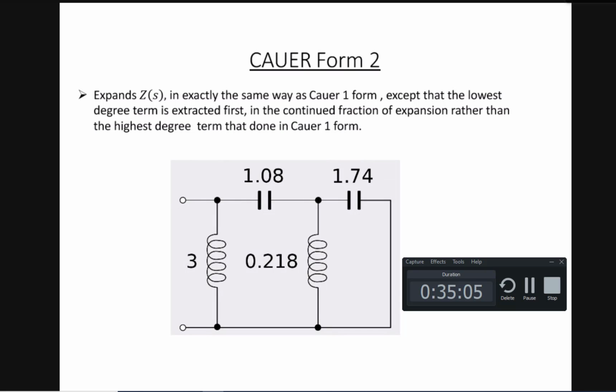Any simple application in practice, can you guess? Otherwise, can you tell if you know, or can you guess what is the use of this network synthesis? Basically what it deals with is, if you know a network function, if it is a positive real function and the denominator is a Hurwitz polynomial, and if it meets the conditions, then you can synthesize a network for that function, right?